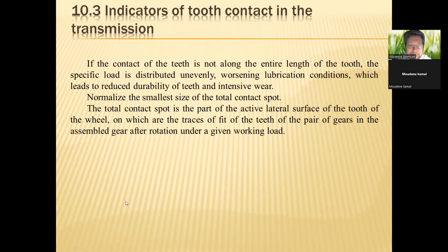If the contact of the teeth is not along the entire length of the tooth, the specific load is distributed unevenly, worsening lubrication conditions, which leads to reduced durability of teeth and intensive wear. Normalize the smallest size of the total contact spot.